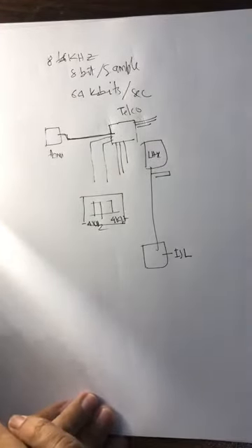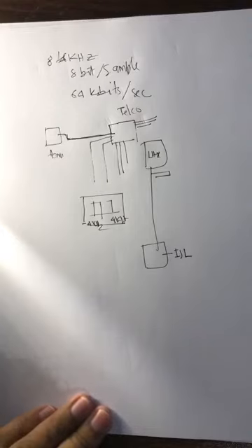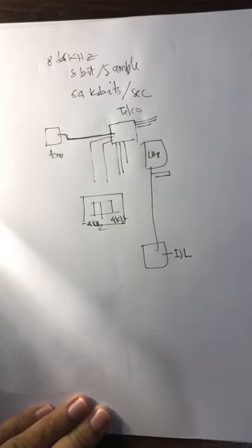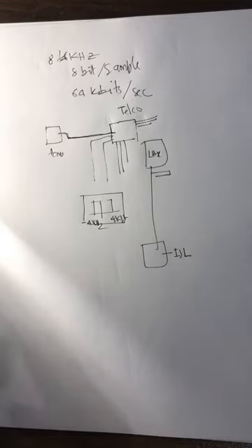A question that I was asked during the question and answer session: looking at the sampled signal, can we know that the signal has aliased? No, not at all. Absolutely no way. You cannot figure out by looking at the time domain signal that it is aliased. Yes, if it is audio, if you listen to it, you may be able to find that out. If it is an image and you view that image, yes, there is a way that you can figure that out. But otherwise, humanly, it is not possible for anybody to look at a signal and tell.